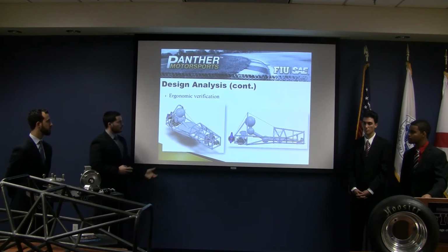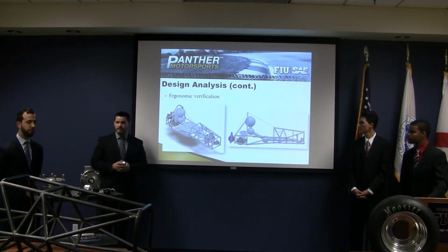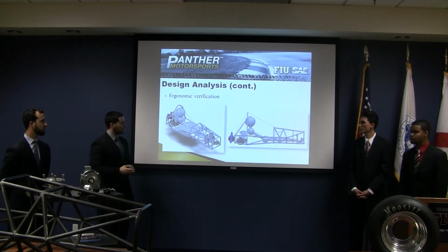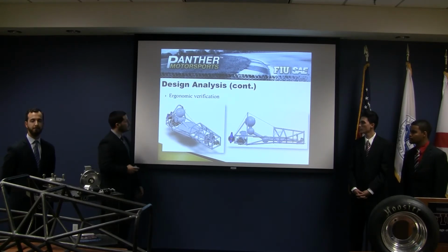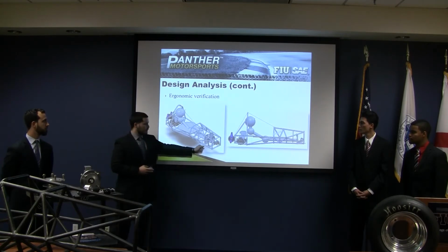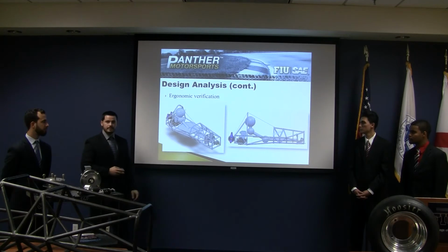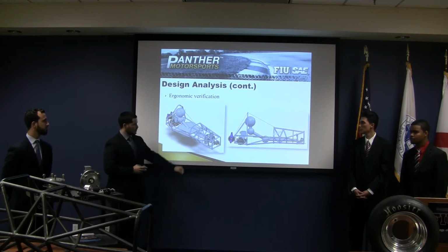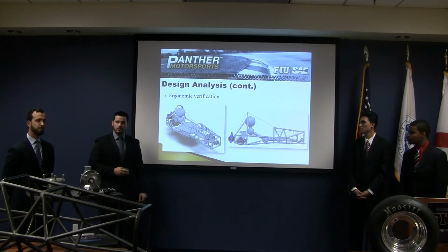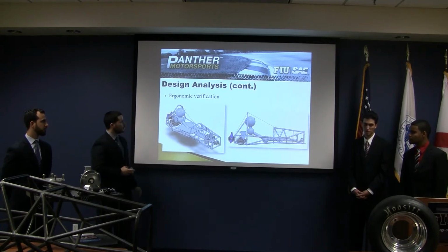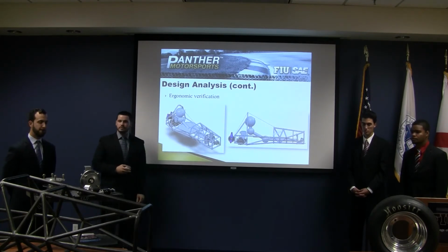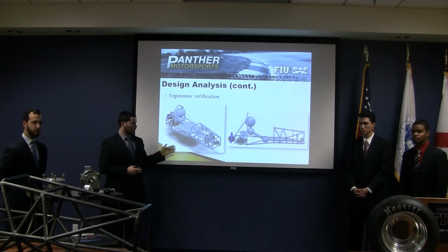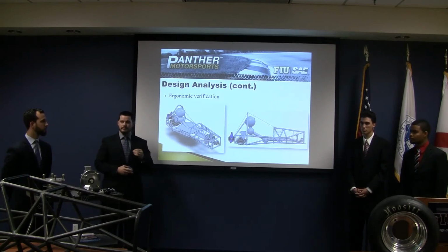And here we were going to go over some of the ergonomic verification we did on the chassis. When working with the Formula FSAE team, you have to consider all components of the vehicle. So we've included both the drivetrain, the powertrain, the pedal assembly, we've also included some templates which must be fitted into the vehicle in order to pass technical inspection. We've included the cockpit opening template, which must dip below the upper side impact member in order to qualify for the dynamic competition. We've also included the leg intrusion plate, which must reach within a 4-inch margin of the rearmost pedal in its inactive state.